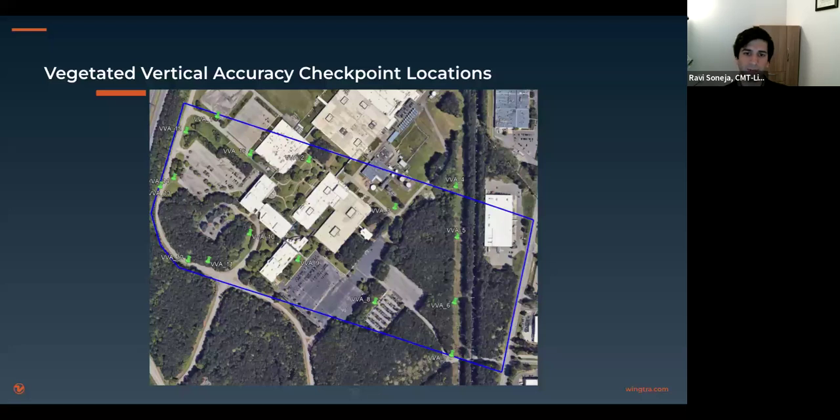you might put it every, I don't know, I'd have to go back and look at some of the stuff I've done in the past, but for at least a corridor transmission line, we would stagger the control down the right of way, just jumping back and forth across the right of way. I'm not sure on the spacing. It also depends on how you're setting that control, and on the number of lifts or flights that you have. When you've got multiple flights that cover an AOI, you do also want to try to have control between those lifts to help calibrate that area as well.